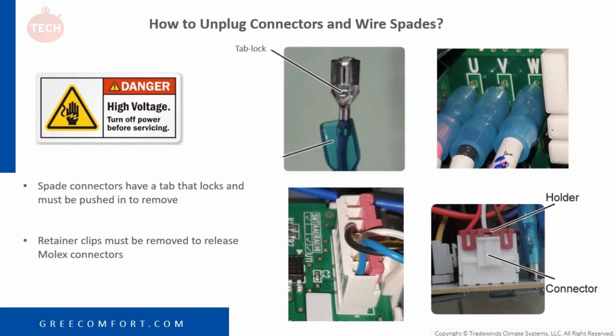So what you want to do is slide that rubber back, and then there's a little tab lock that you push with your thumb, and then you can unplug it. Don't try to manhandle those. You will break either a board or break the spade.